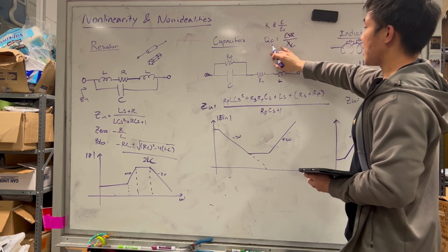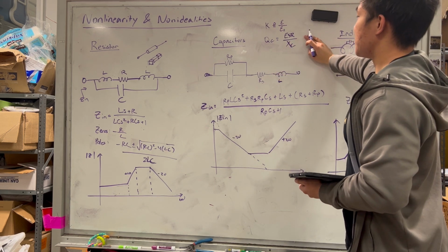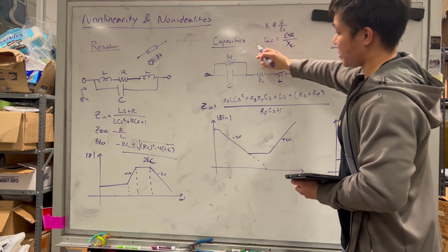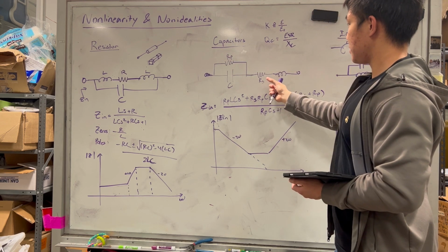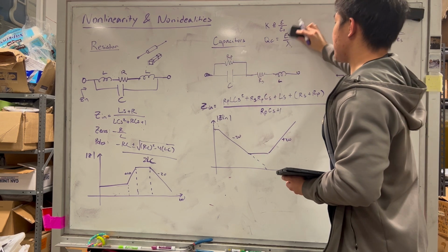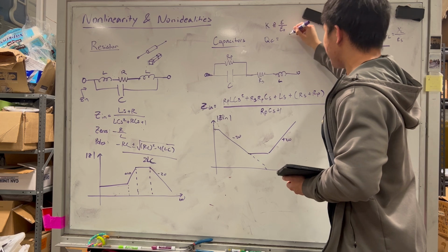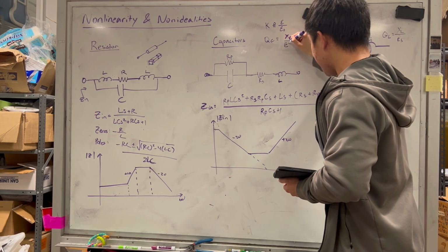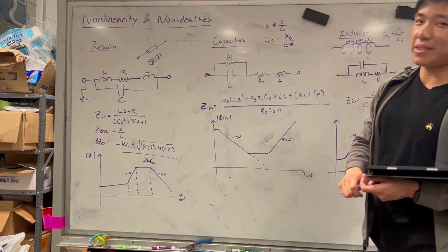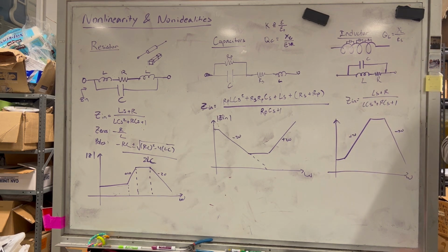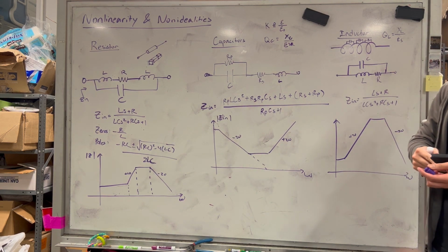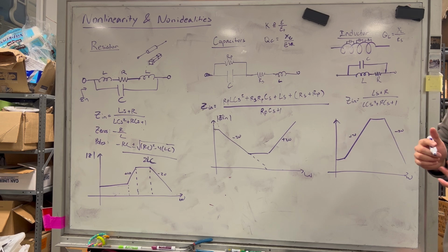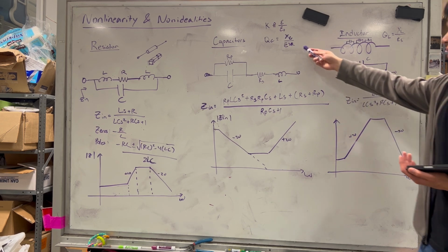For a high quality factor, ESR should be ideally infinite. Oh wait, no, this is right, sorry. ESR is equivalent series resistance. Normally when we think about quality factor for a capacitor, you think about the capacitance in parallel. But ESR, which is what you give in data sheets, is actually in series. That's why it's like this.